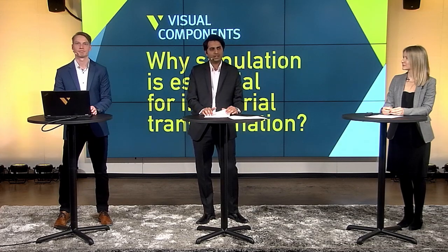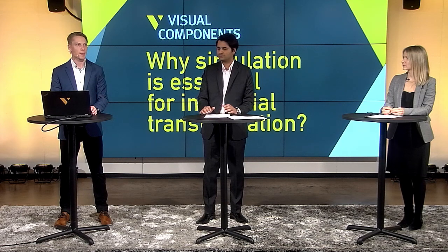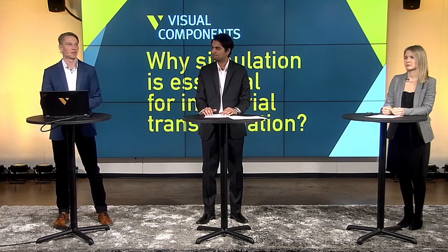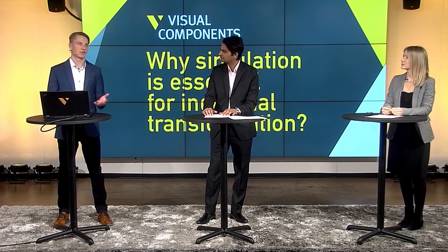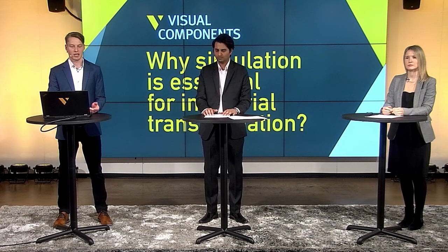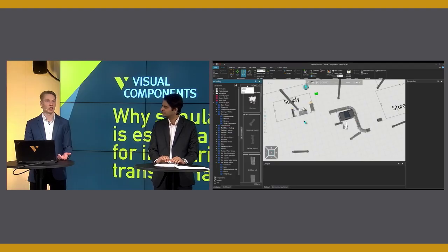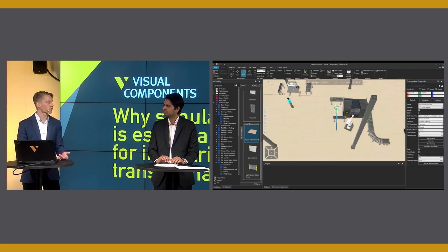Right. After the concept is done, how do you control the details, like, for example, robot programming or these kinds of routines? The robot arm in the machine tending cell moves automatically. It is also possible to manually program the robot and create routines. In the simplest case, programming is used to reach the idle or home location for the robot when no actions are required.